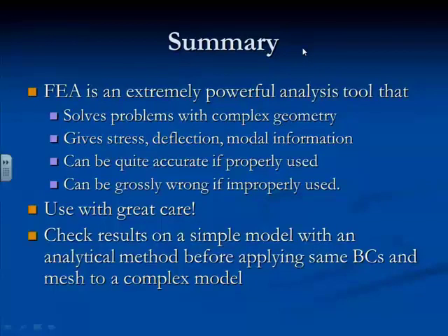In all the cases I've run into in recent years in which I've been asked to check something, I did one over Christmas, they did an FEA analysis. In one case, they screwed up the boundary conditions, and the results were wrong. So the first thing I always check is the boundary conditions. Sometimes it's quite obvious, because if you look at the deflection plot and you expect there's a pin support at that place and you see zero slope on both sides of it, there's something wrong. I should not have zero slope across a pin, right? It should be going either like this or like that. As soon as you see that in the plot, you say there's something wrong. So you have to check that from a common sense standpoint as well.